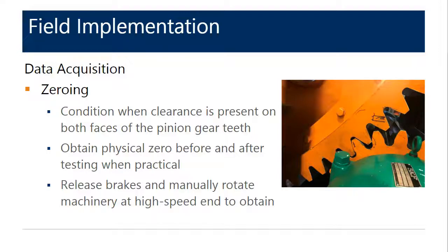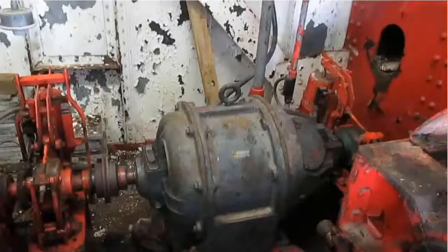With the gauges installed, a zero obtained, and the position indicators calibrated, we are now ready to record. Both shafts and the position indicator are recorded simultaneously. The following example videos depict the recording process for a bascule leaf and then for a vertical lift bridge.